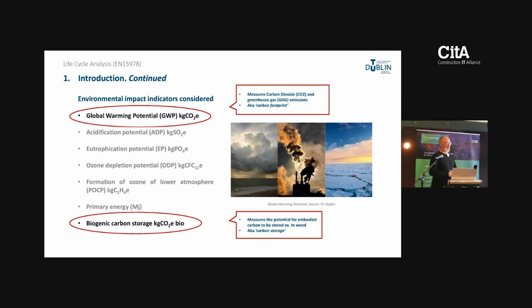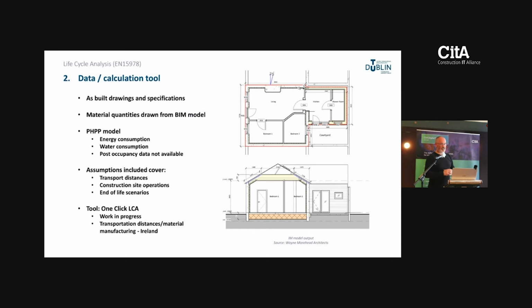This is the cottage. I should say that it secured no grant aid from the government whatsoever because we were using low carbon materials: wood fibers, cellulose, post-consumer waste materials, limecretes, LECA expanded aggregate in the floor, all of the materials that were actually appropriate and breathable for that building. We couldn't get grant aid. If we had used expanded polystyrene, polyisocyanates, phenolic, etc., we would have been able to secure some amount of government grant aid. And that's an uncomfortable thing to say, but it's true.